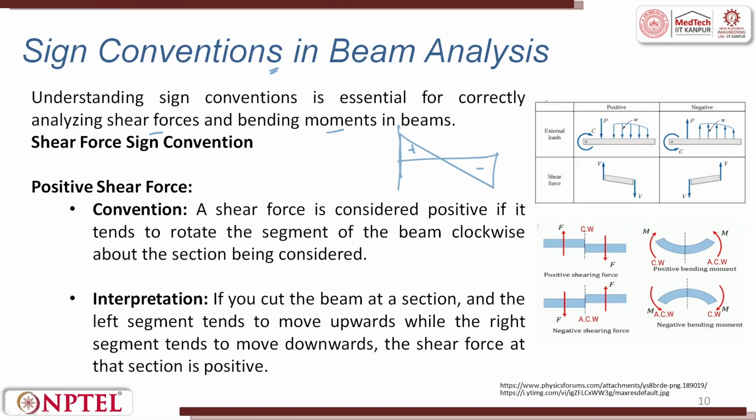But in reality, you can have a beam which is fixed, wherein you can have UDL, then you can have a point load, and then from here you can have a varying load, and here you can support it. So, here you will keep it as free, right. So, in one beam itself you can have all the three loads coming into existence. If that is the case, then we should follow the sign conventions properly.